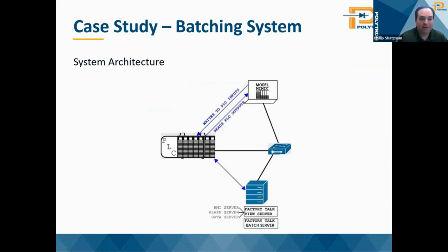The PLC is running the actual code that you'll be running in the field. And this is what makes emulation so valuable, the fact that you're running the exact code you'll be running, and you get to see how that code reacts ahead of time. The blue arrows here represent the logical communications between the components. Just like in the real world, the servers and the PLCs talk to each other, exchanging information needed to display the system status for the HMI and also for control.